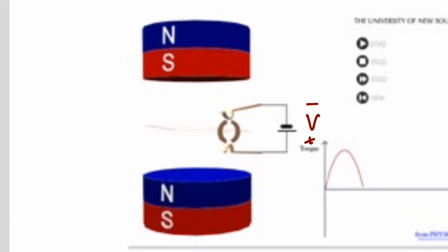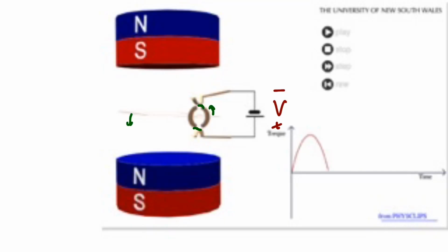And when it has rotated to this position, if there was still a current flowing, there would not be a torque because the magnetic dipole moment would be in the same direction as the magnetic flux density. But at this point, the commutator comes into play, and you see that the electrical connection is broken between the battery and the current loop, so the current will quit flowing, but because of angular momentum, the loop will keep rotating, and then the connection will be reestablished, but now with the current flowing in the opposite direction. The magnetic dipole moment had been pointing in this direction.